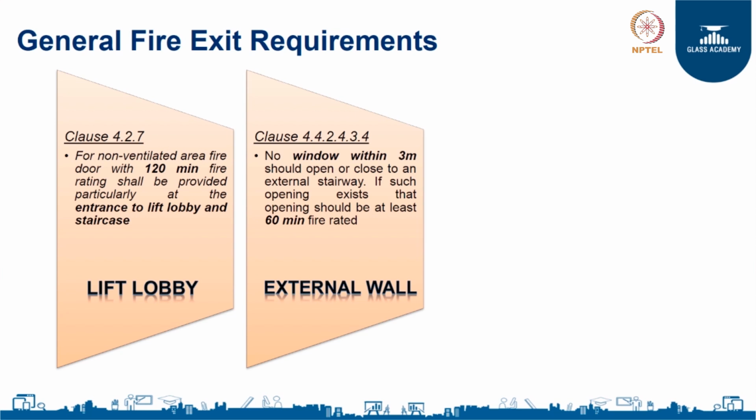Similarly, it says that no window within 3 meters should open or close to an external stairway. If you have any window opening to an external stairway, there is a possibility that the fire could spread into the fire exit passage through these windows. Or if you have such windows, they should be at least 60 minutes fire rated, because 60 minutes gives you enough time to evacuate all the occupants.